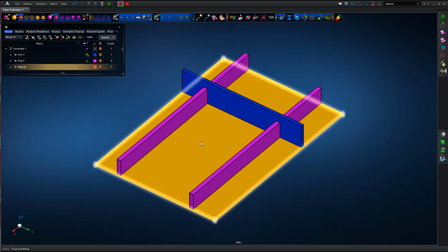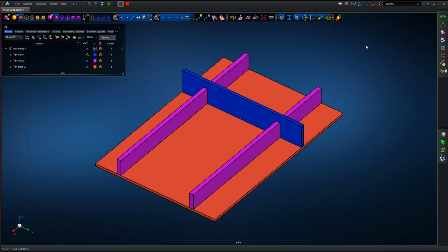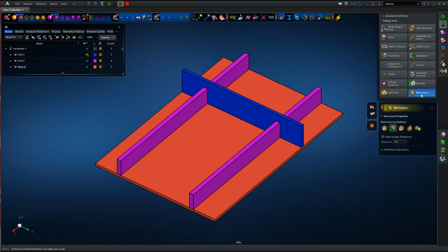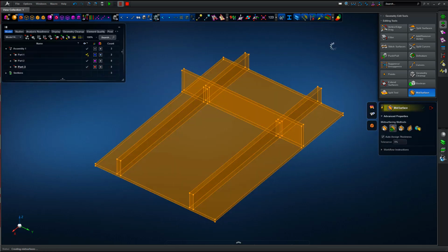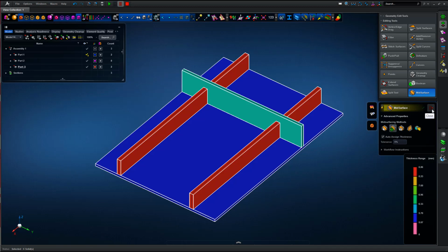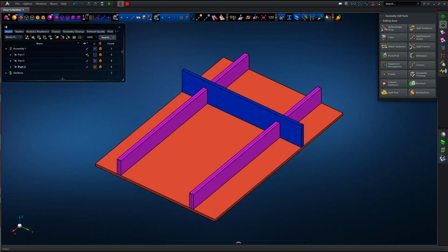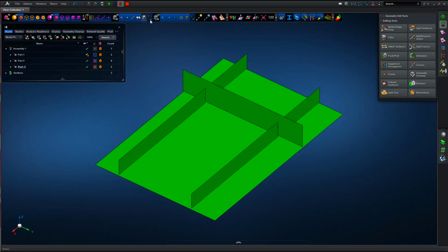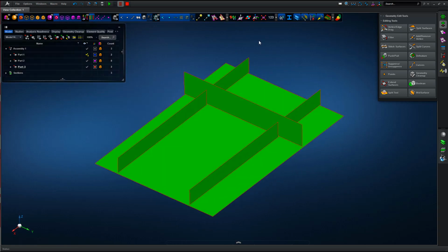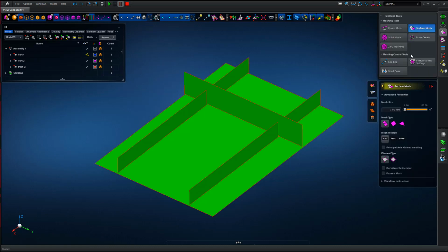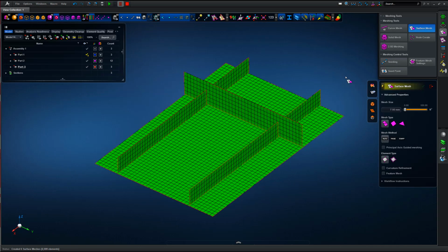and then press record. So now we're in recording mode, and again the pause and stop button is shown on the top menu bar. Just going in and mid-surfacing with the auto assign thickness turned on for this simple example. So we've got the mid-surfaces generated, hiding the solids and showing the surface edges. We've got 3 edges, no congruency between those surfaces at this stage, and then the surface mesh using the default parameters, so 7.5mm element edge length, mesh those surfaces.